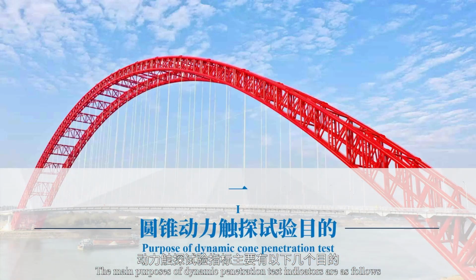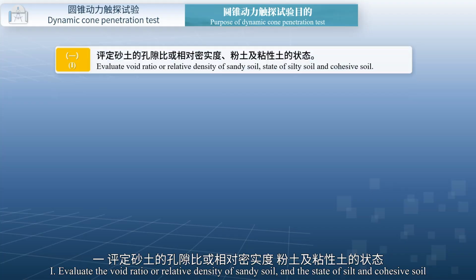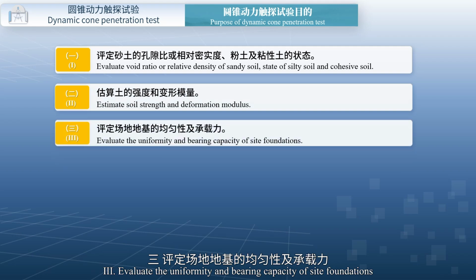The main purposes of dynamic penetration test indicators are as follows. First, evaluate the void ratio or relative density of sandy soil, and the state of silt and cohesive soil. Second, estimate soil strength and deformation modulus. Third, evaluate the uniformity and bearing capacity of site foundations.